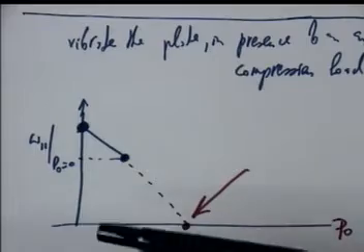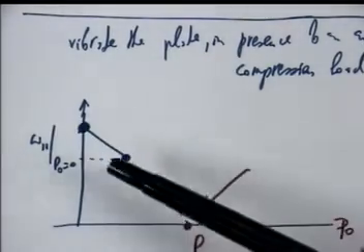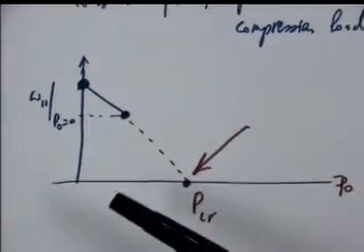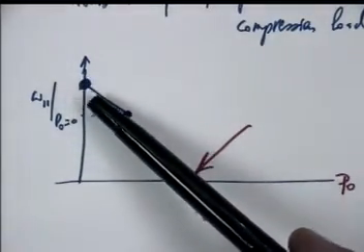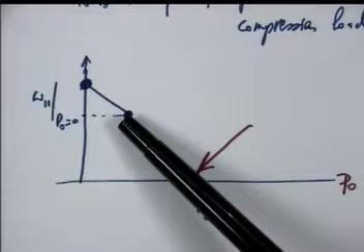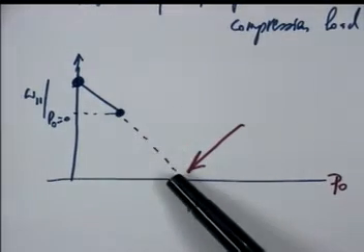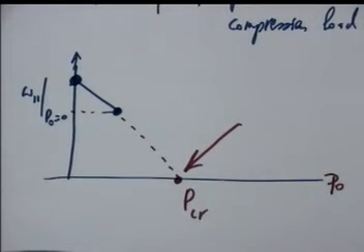And at that load, just calculate the frequency. Okay? Then just pass a straight line between these 2 points, and then continue the straight line. Wherever the straight line hits the horizontal axis, that is where the buckling load is, because we established before that the relationship was linear.